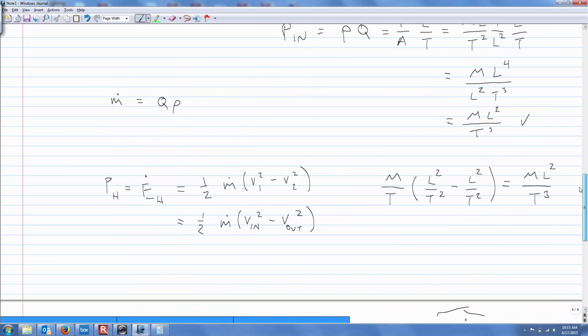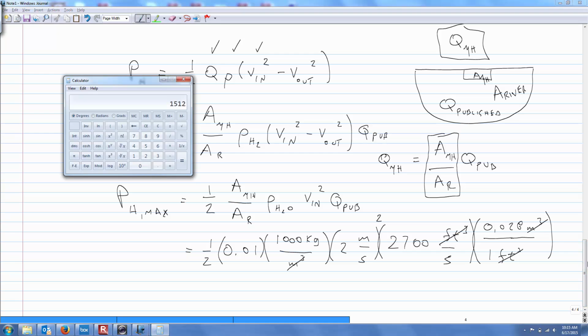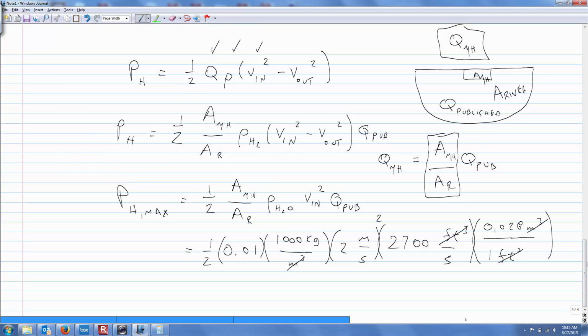One thing I would recommend for you guys, because I know you're kind of at a crossroads here, most of the woodworking is done, so now you're looking at components and stuff. One of the things I would do is get some baseline numbers. That electric motor, the trolling motor, hook a meter up to it, spin it. Take a drill, it fits right on the shaft, and spin it. See what kind of numbers you get, see what kind of RPMs you have there.